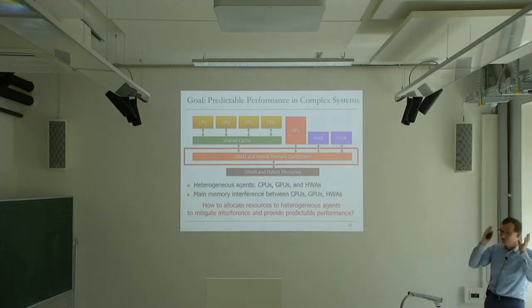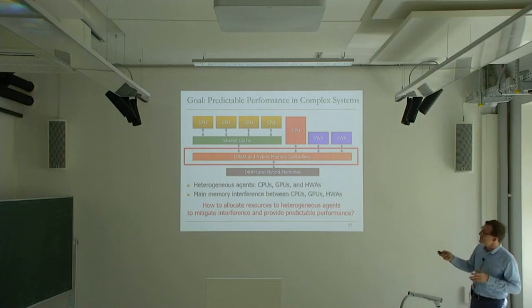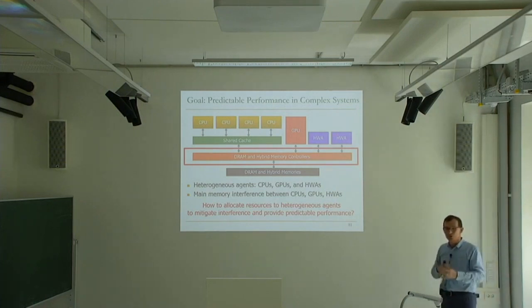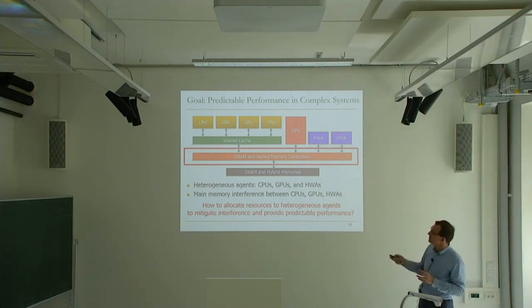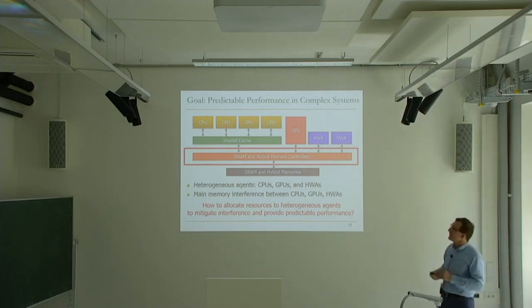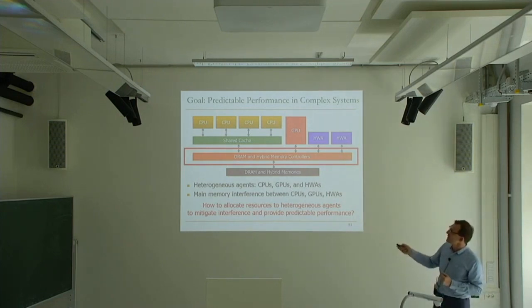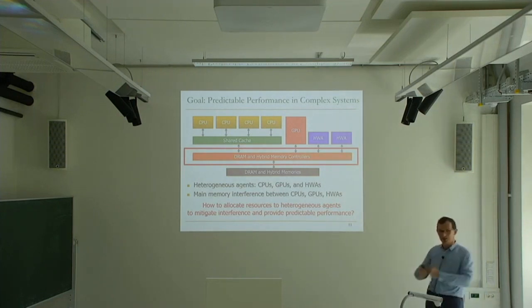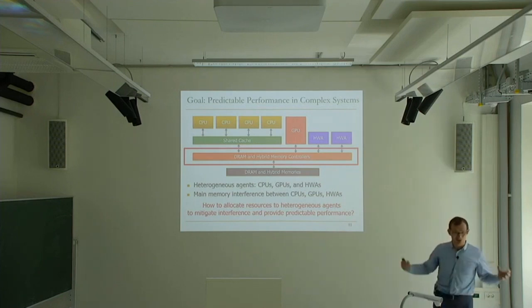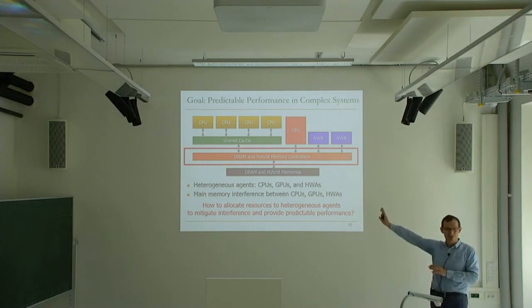In fact, since we're dreaming, we didn't do this yet, but I think it makes a lot of sense for memory controllers to be configurable also, because sometimes you want algorithms in the memory controllers that depend on the application that you're running. If you can somehow instantiate a memory controller algorithm based on the application that you're running, you can do much more, as opposed to having rigid algorithms that are designed by some random hardware designer that thought it was good to design that.